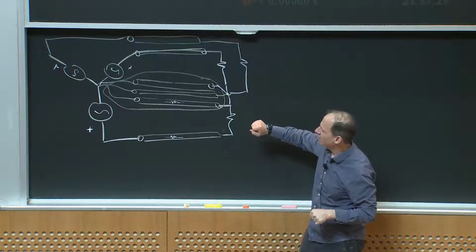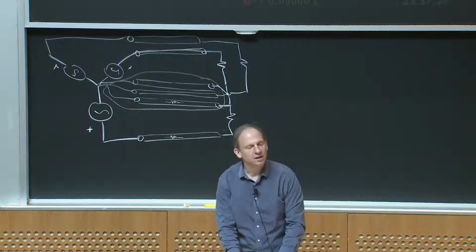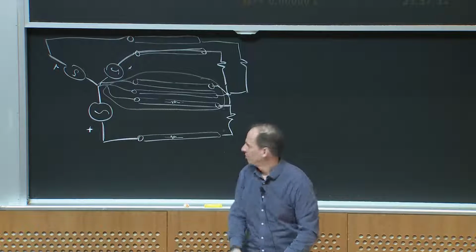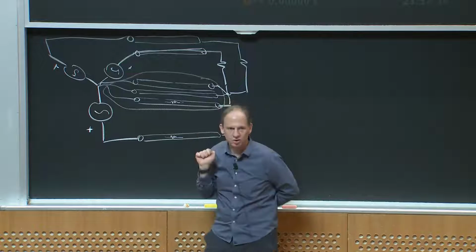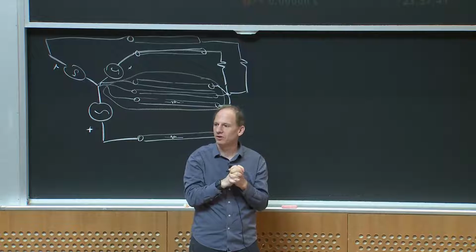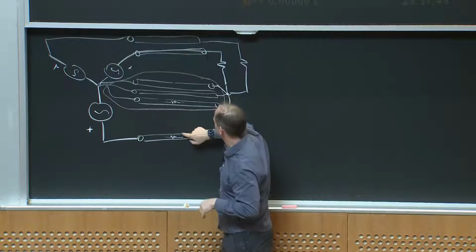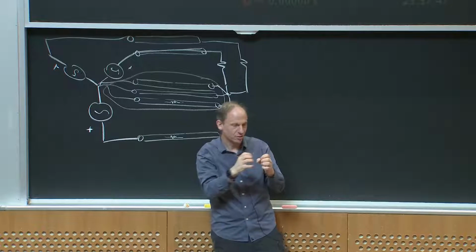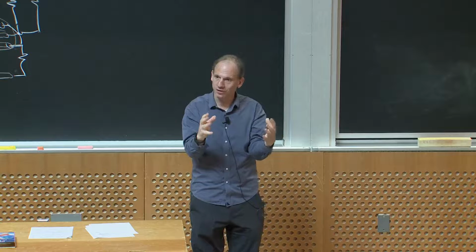While I haven't calculated it for you yet, the voltage rating between this phase and say this phase is actually the square root of 3 Vs, okay? So it turns out you need a little bit more insulation if you're going to put this conductor right next to this conductor than if you put this conductor next to the ground, right? But if I cared about insulation, I could just turn down the voltage, right?